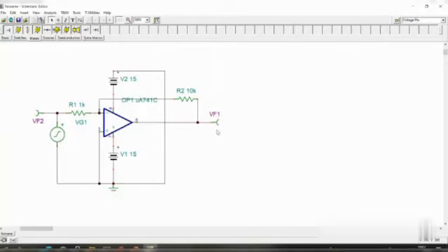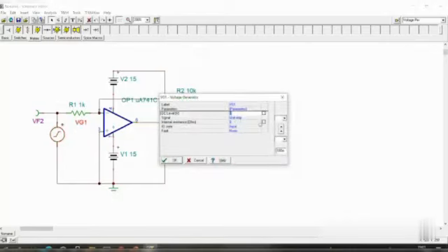So as an amplifier, you need to see the input as well as the output. And finally, the input is to be set. Here, by default, the TINA voltage generator will give you a unit step input. But unit step is not the input for an amplifier.